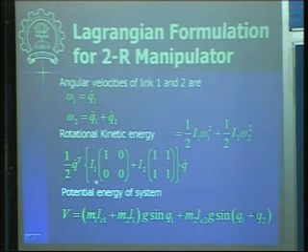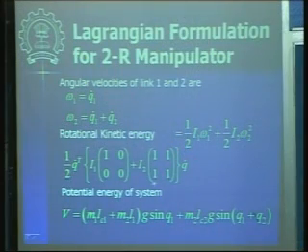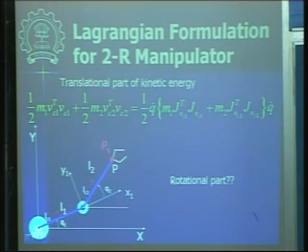We have expressed it in the same form as the previous form, which is q1 dot transpose multiplied by some matrix into q1 dot. So that way it will be very easy to now identify the terms in the D matrix, by taking summation of this part and this part in the translational case. So you sum up these two and you will get your D matrix.